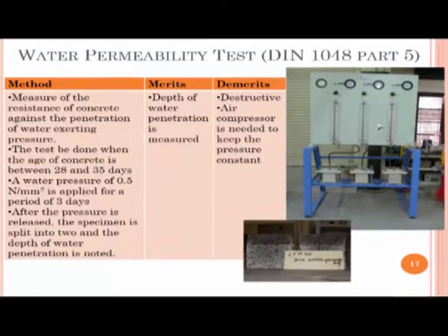So the water permeability or water penetration test is done as per a German standard, which is DIN 1048 part 5. It is a German standard which is now also a European standard or EN standard. Okay, so this is the equipment for it.